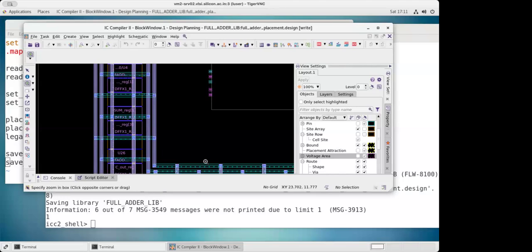You will be able to see that. Yes or no? Yours is not working? Yours is working, then run this particular placement. You did it? Legalize placement is also done. Great. Now maybe you can remove it, unselect it and check it.